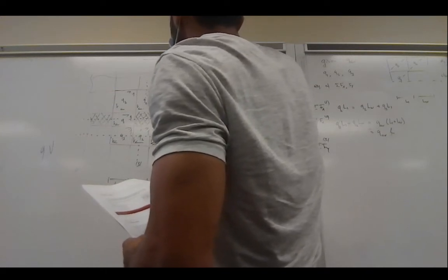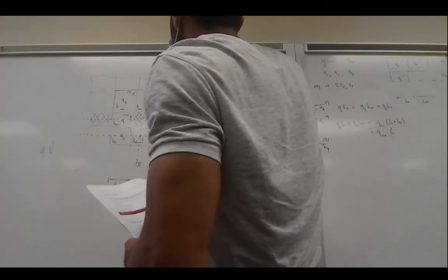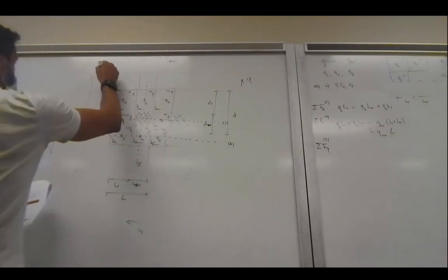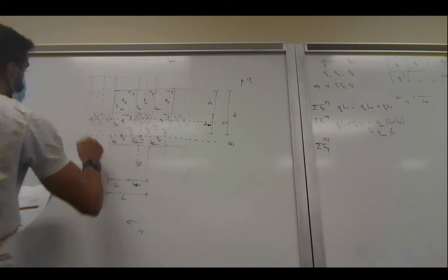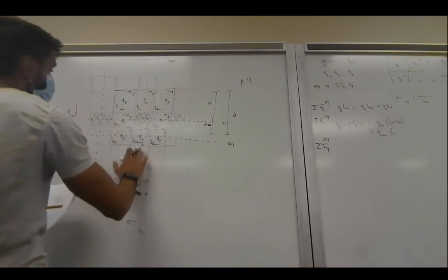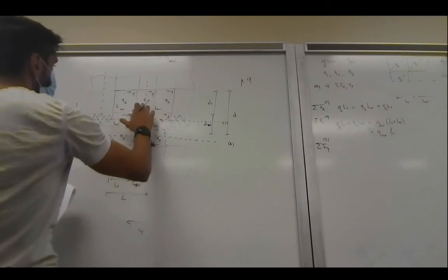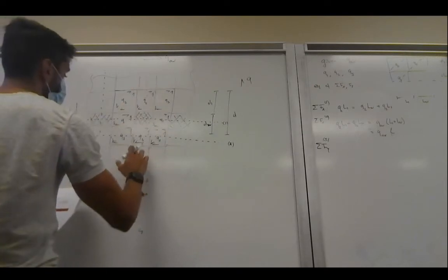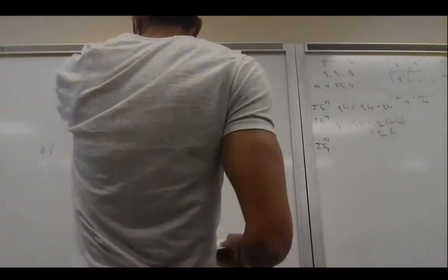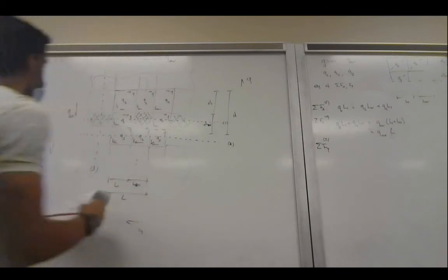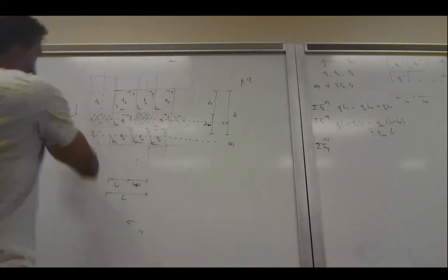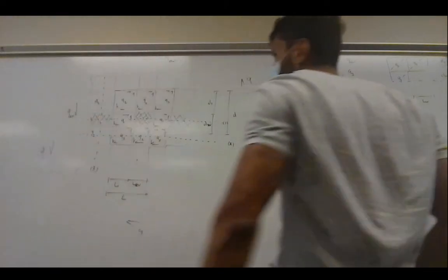We do it here because then we know what our average shear flow on this side is. So we will have only Q2 because this cell is again Q2, Q2. We have our average shear flow acting on that far side.